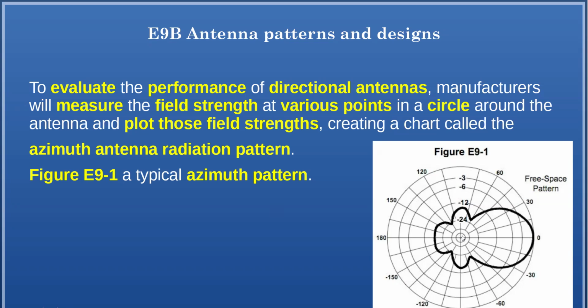Typically, that would be what you see with a Yagi or a quad loop. You can do this by hand, by going around doing the measurements, or you can do it from a modeling program like EZNEC, probably the one most people use, and there are different variations of user interfaces for it. But this is a fairly typical azimuth pattern for a beam antenna.